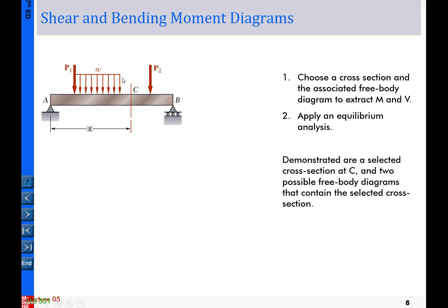The principle basically is this: we are given a beam, and under certain given loadings, that could be combined point loadings, as well as certain types of distributed loading. Okay, then drawing the diagram is this. The first one, we simply pick a section arbitrarily, and that section has the coordinate x. We simply measure from A to here. That is the measurement. Okay.